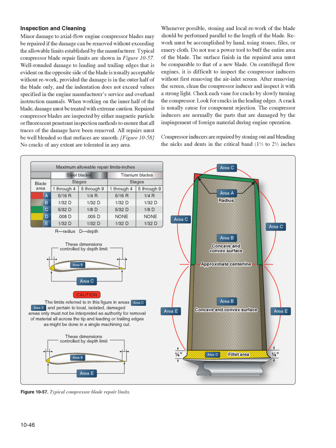Whenever possible, stoning and local rework of the blade should be performed parallel to the length of the blade. Rework must be accomplished by hand, using stones, files, or emery cloth. Do not use a power tool to buff the entire area of the blade. The surface finish in the repaired area must be comparable to that of a new blade.